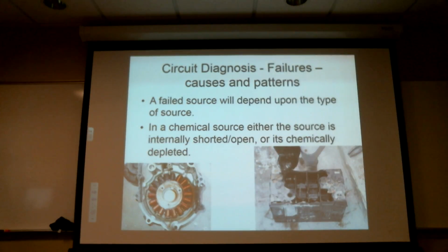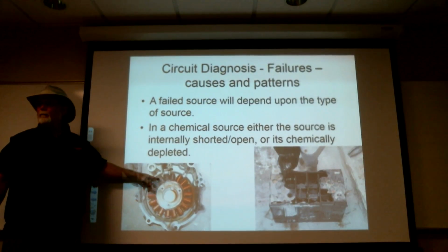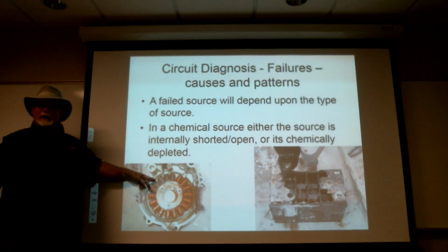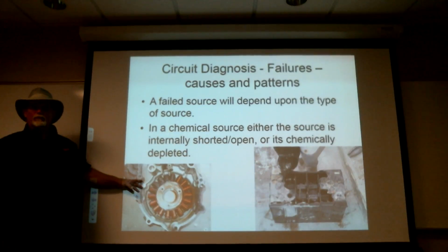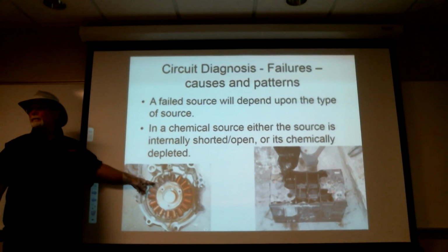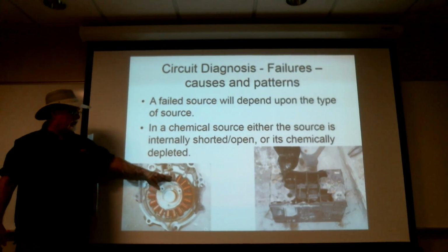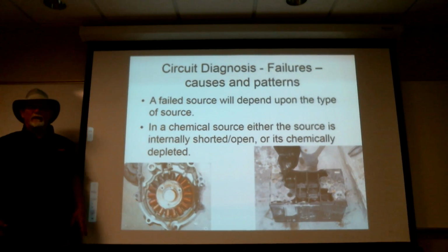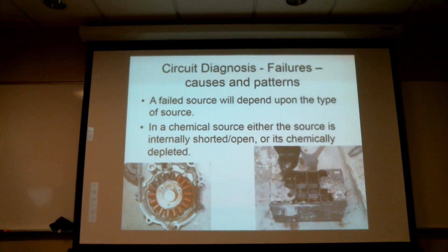Power sources can be a variety of things. Again, in all likelihood, we had a short in one of these. It started getting hot because all the power being generated by all the rest of them was being driven through the short here. As it got hot, it burnt insulation, shorted more. It started burning insulation in other ones, and they started shorting. Okay, this problem continued for a while. On the battery,